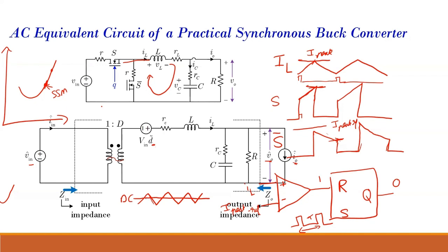Another is AC mode, where it will remove this DC component, and that will be at 0, and around 0 it will show the behavior. So it will remove the DC component and show the AC component of the signal. Yeah. So basically the AC just signifies the variations and the ripple around the DC steady state value.